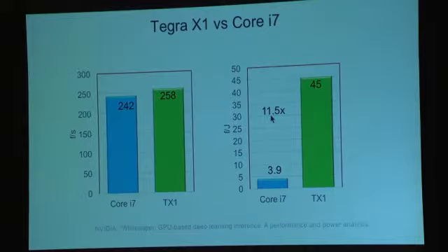And the reason is that they eliminate a lot of the overhead that's found in CPUs. CPUs basically have enormous amounts of hardware that's all there to handle the problem that when you do a memory load operation, you don't know whether it's going to hit in the cache and take 3 cycles or go all the way out to DRAM and take hundreds. And because of that, no matter how much work your compiler did to schedule the computation beforehand, they reschedule the computation in hardware at runtime every time around the loop. And that's computationally very intensive and energetically very intensive.